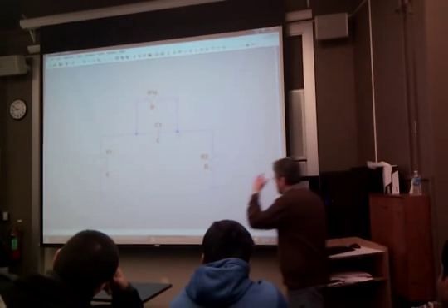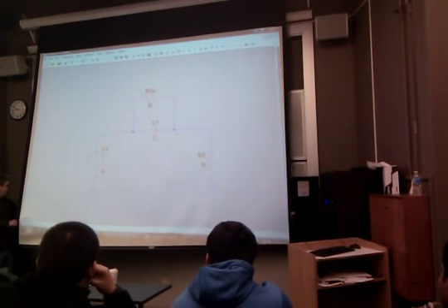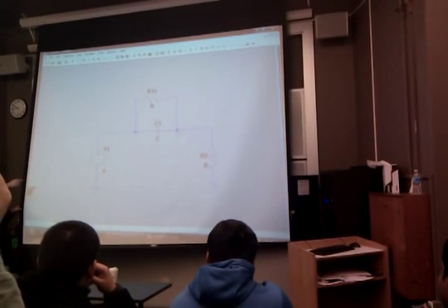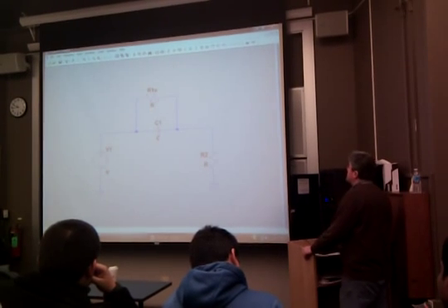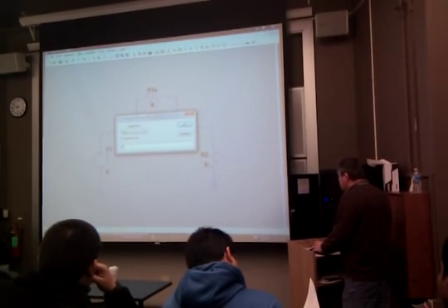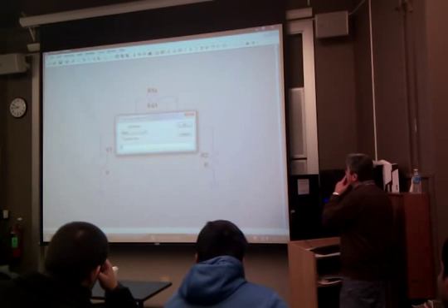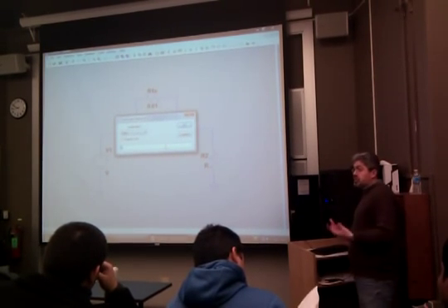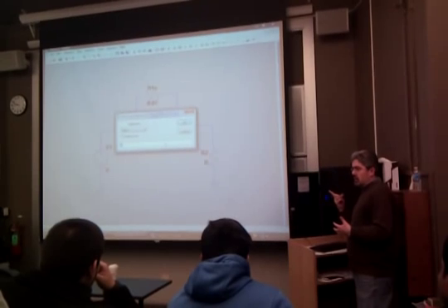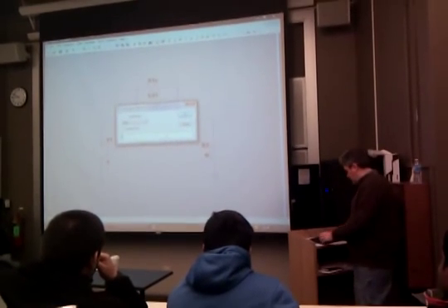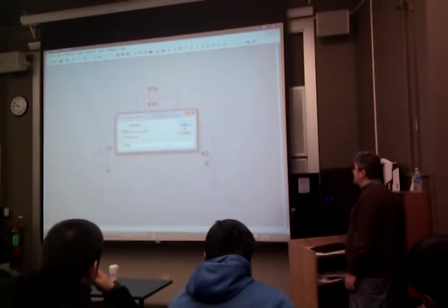Okay, what should I put as component values? I'm going to choose what I had over here. I'm just going to use those exactly. I'll use 10 to the minus 2, so this is 0.01. Okay. 1 farad. And then I'll use 1 over 900. You can actually put in fractions like that, but they need to be computed, so the directive to ask LTspice to compute something is to put in curly brackets. So if we do curly brackets 1 over 900, it'll actually compute that value.